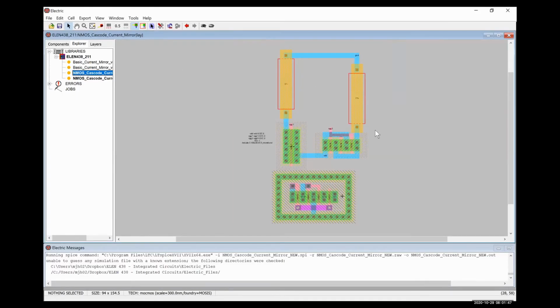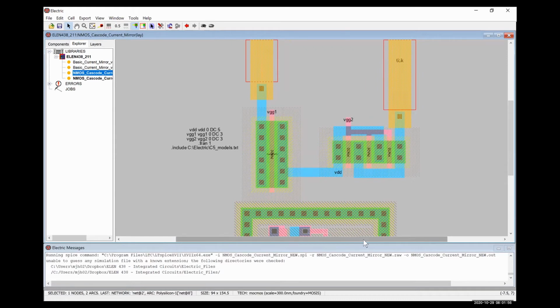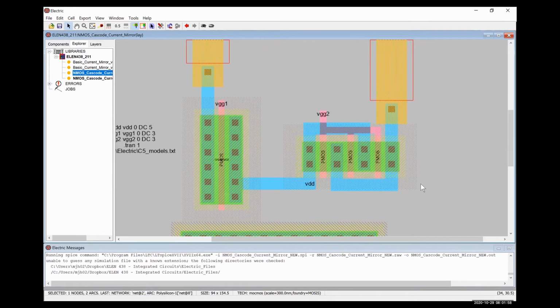So couple of things. A big one is that I figured out what the problem was that I was having the other day and why my currents and all that kind of stuff didn't match. I guess I was just having the biggest brain fart in the world. When I kept putting those other transistors and attaching them in parallel, that was just making this transistor larger and larger. So obviously, 3 10x2 transistors in parallel should be the same as a 30x2 transistor.